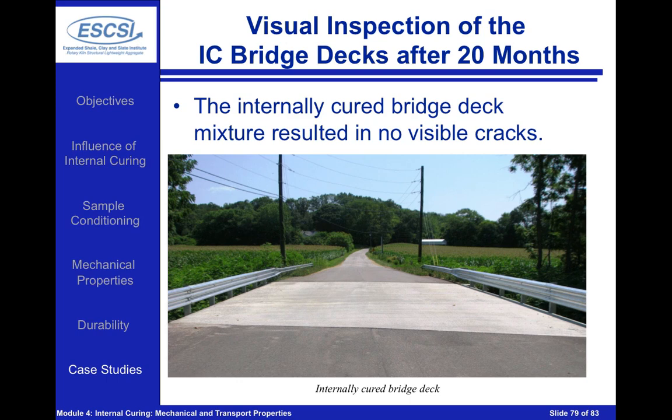Here again, the main takeaway is if the concrete cracks, it's going to allow the chloride ions in at a much faster rate than in an uncracked concrete, and that can play a role in the service life. Now I want to be very careful that even though this particular bridge deck showed no cracking when it was internally cured, we need to remember that cracks can occur for other reasons other than just shrinkage. So we need to be very careful to understand that while internal curing can help to dramatically reduce our shrinkage cracking, it may not prevent all the cracks that can form in the system.